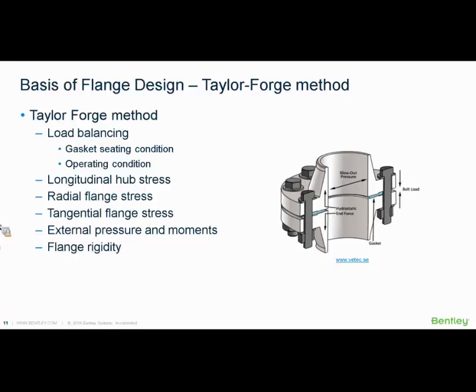There are other methods like the newer EN1591 method available, which employ a more complex model for the bolted flange and take into account the deformation balance along with the force balance. And of course, a full finite element analysis for a single flange can also be employed.